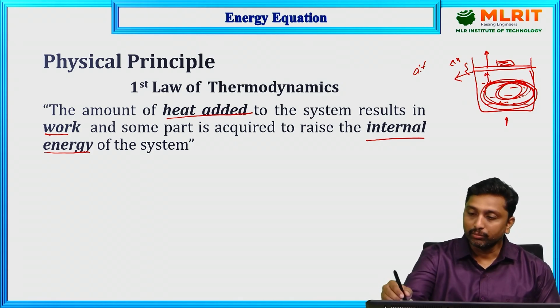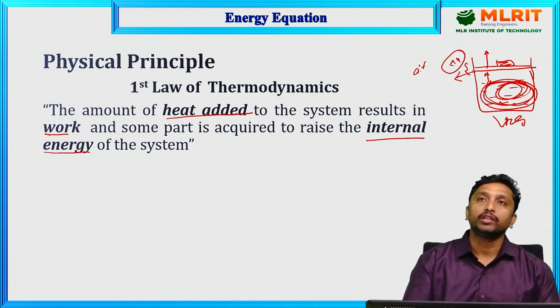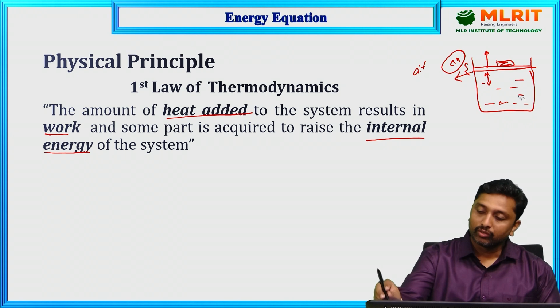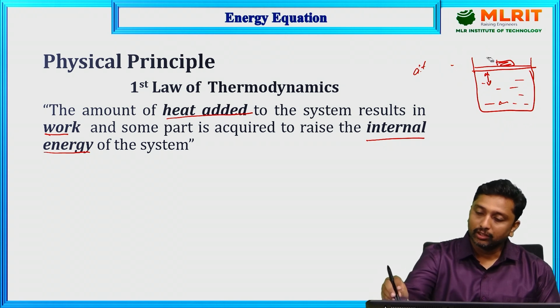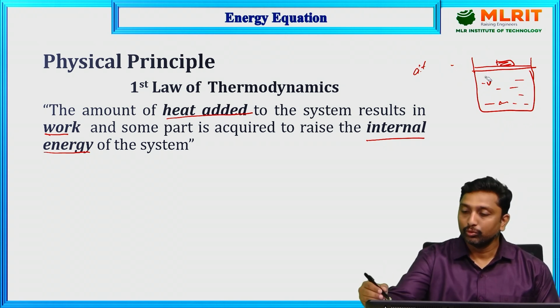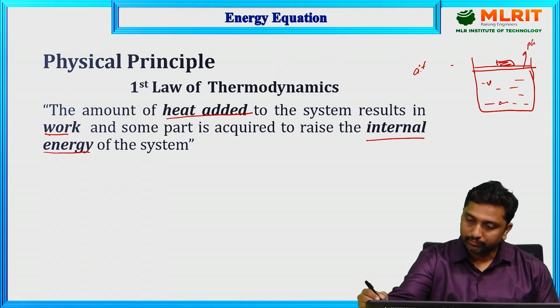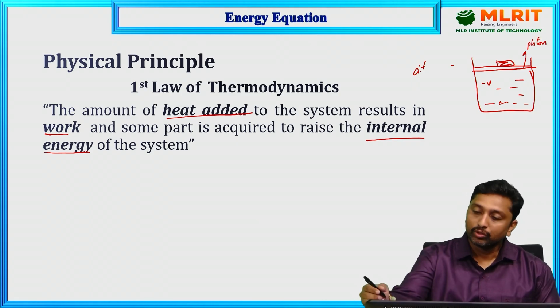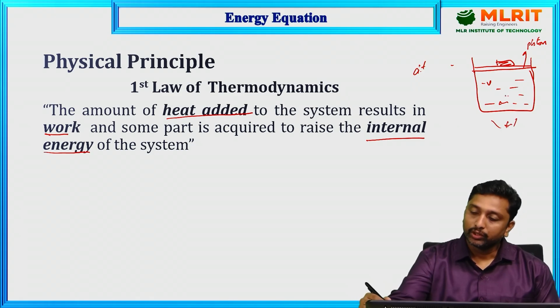So whatever heat energy is added is converted into raising the temperature of the fluid, and work is done by pushing this piston. Whatever heat is supplied will be converted into raising temperature, which is increasing the internal energy of the system.